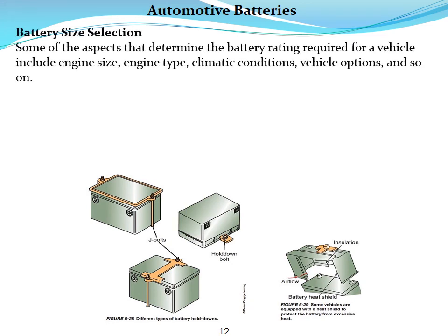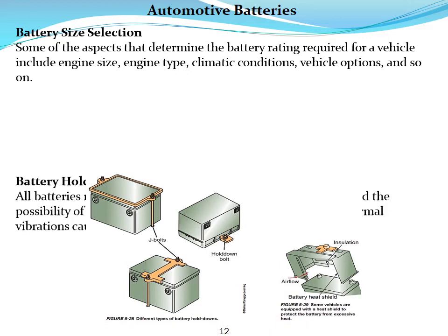Battery size selection. How do we choose the appropriate size for the battery? Some of the aspects that determine the battery rating required for a vehicle include engine size, engine type, climatic conditions, cold or moderate weather, vehicle options, and so on.